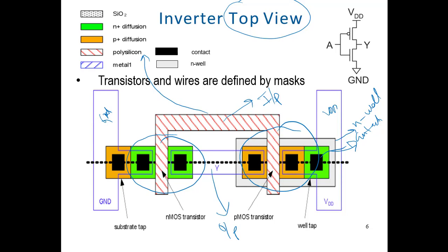So these are the metal contacts. So for example here it shows that the VDD or supply is shorted with the source of PMOS. So it is basically showing this point. So we have the source of PMOS, it is shorted with the supply voltage. I hope that you can make sense of other points.